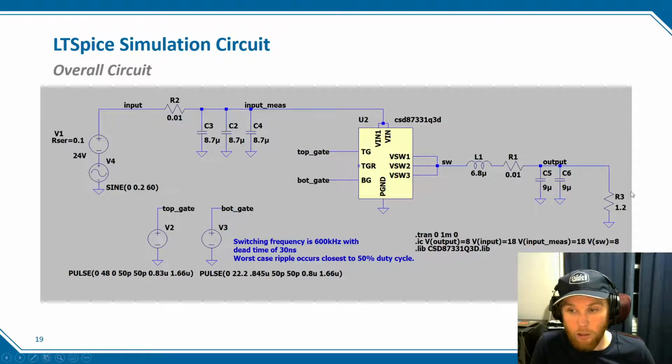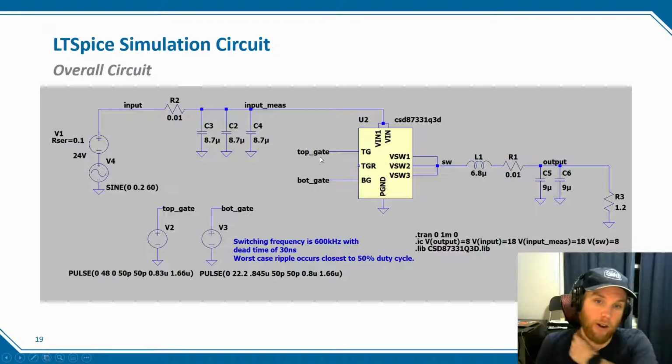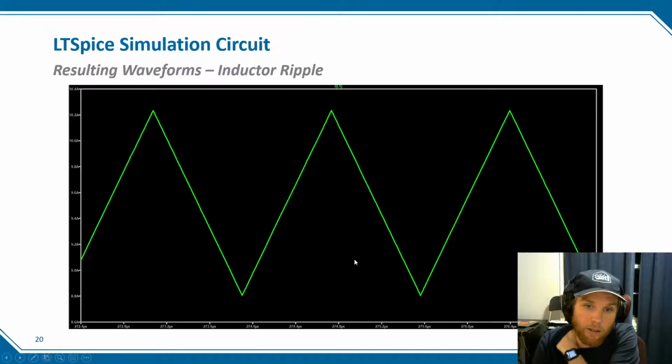As well, usually lithium-ion cells are modeled as constant current sources in simulations, but that was giving me some really weird transients. So I just used a resistor, so those would be damped away. And then finally, you can see here this .IC. That was used to initialize all the different nodes at their voltages so that it would start from a steady state since the charge controller handles soft start of the buck circuit.